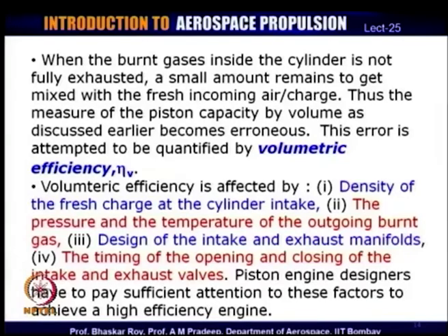So, all the burned gases do not go out of the cylinder, a very small amount remains, and when the intake valve opens and the fresh charge or fresh air comes in, it gets mixed with the residual gases, and as a result what you get finally is a combination of fresh air charge and a certain amount of residual burned gases that has remained after the exhaust stroke.